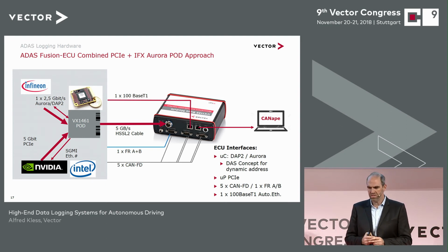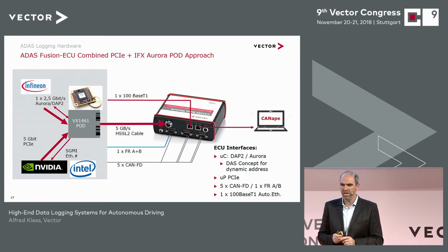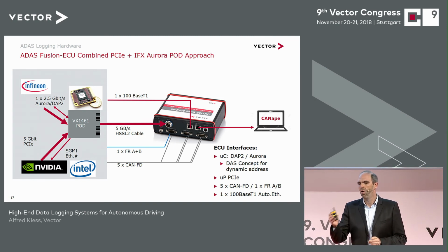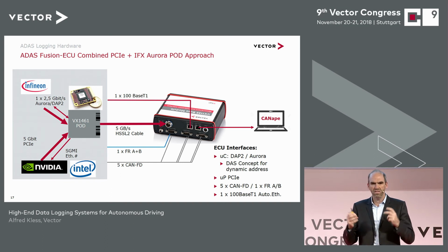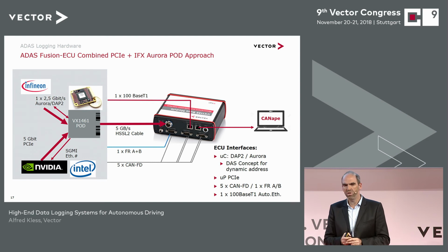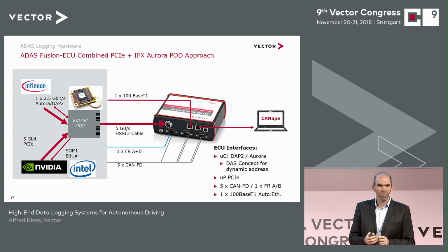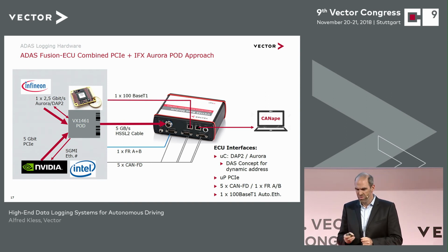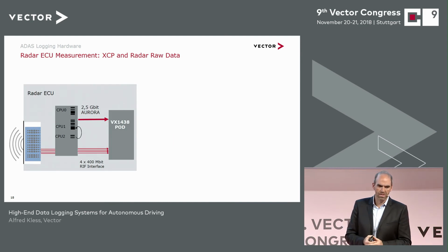If it's dynamic to the compile side, static to the runtime, then this hardware can smoothen things in such a way that any normal tool can be connected behind it, although up front at the compile time, the address allocation is dynamic. Of course, this goes into measurement technology and the Adaptive AUTOSAR stack with the appropriate processors, which then at random, as it were, can link the signals elsewhere.